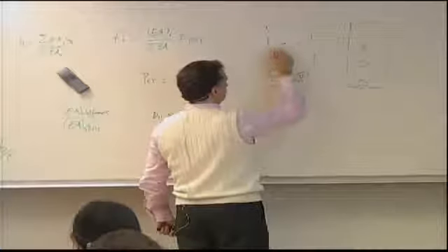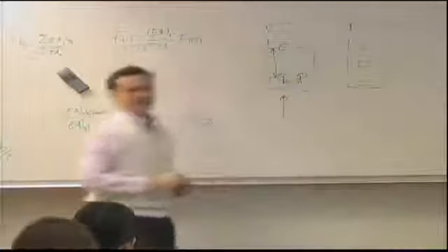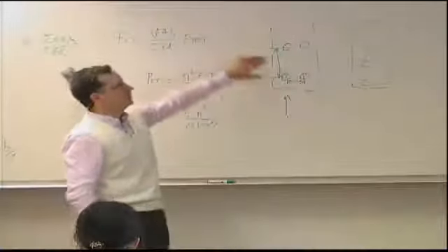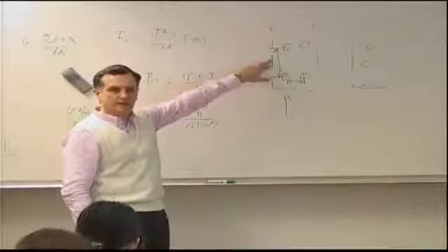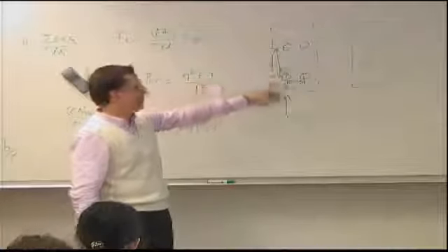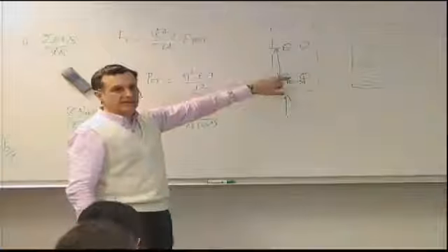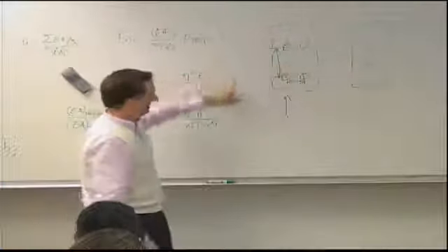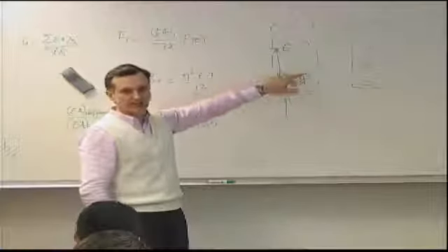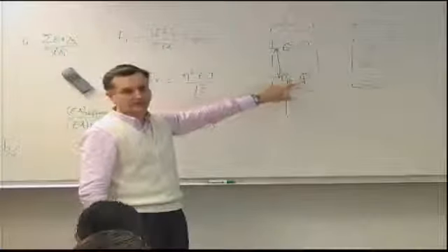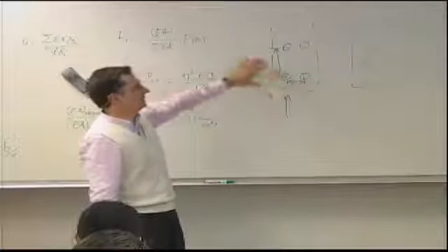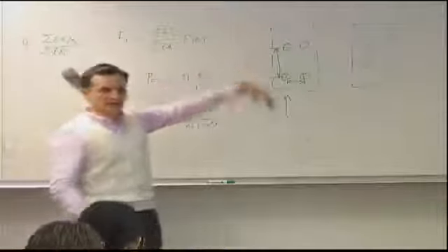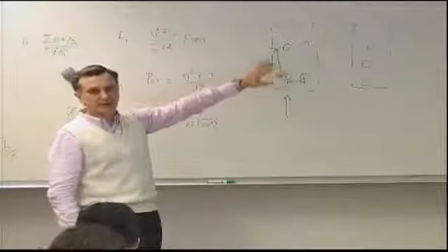Now, there's a rule that covers all this. I mentioned 20 millimeters before as a good minimum distance. The rule is 4 to 5 fastener diameters. Once you pick your fastener diameter, as long as in any direction around it, irrespective of the load direction, the next fastener is at least 4, preferably 5 fastener diameters away, then all the problems that we mentioned with stress concentration effects are almost completely eliminated.